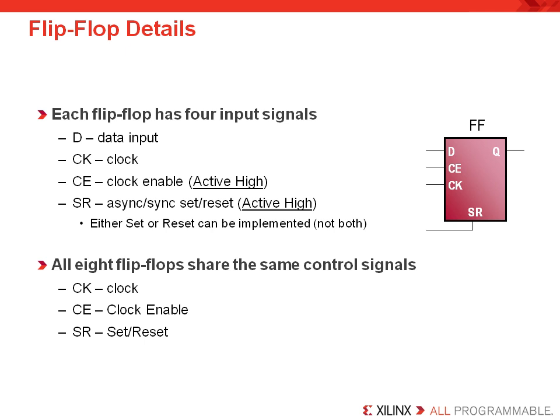This is important because your synthesis tool should be able to map the set or reset to a LUT input if it is designed synchronously. And as you'll see, this will give you some flexibility. This gives you more flexibility and is necessary for the tools to pack the most logic into the FPGA and get high speed, since all 8 flip-flops share the same control signal. So our recommendations are to design for active high control signals and build with synchronous sets and synchronous resets.